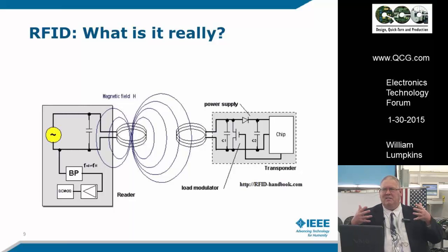When the magnetic field hits a device, through a coupled coil of wire, we have electrical charge that's developed. The electrical charge goes to a microprocessor, powers the microprocessor really quickly, and then it sends out information. Some people relate to this the old IFF systems, identification friend or foe, where it would actually send information back to say, this is who I am.